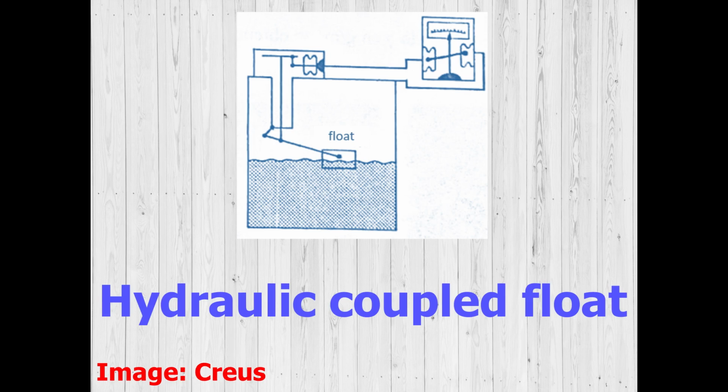The disadvantages are that its installation and calibration are complicated. It has moving parts inside the tank. The float can get stuck in the guide tube by some deposits of solids or crystals in the liquid, and the long guide tubes can be damaged by the sudden waves of the surface or by the violent fall of liquid in the tank.